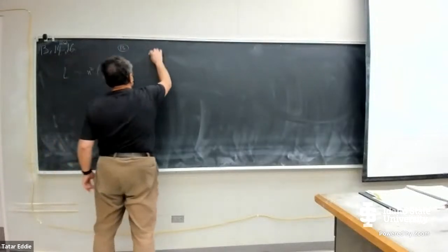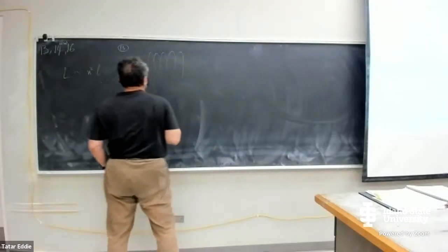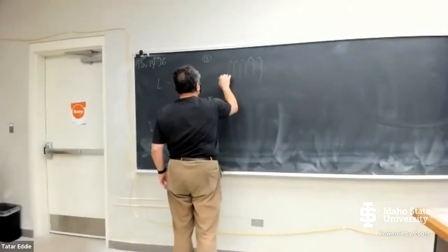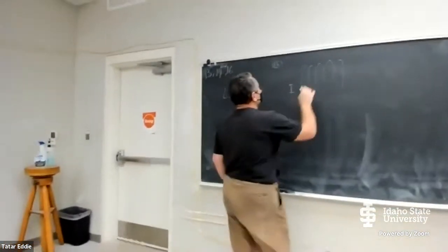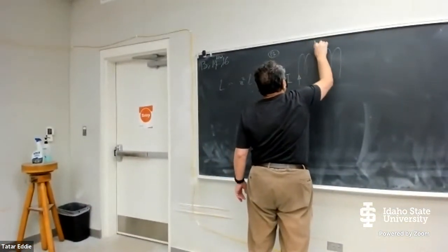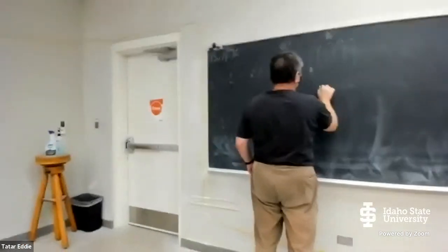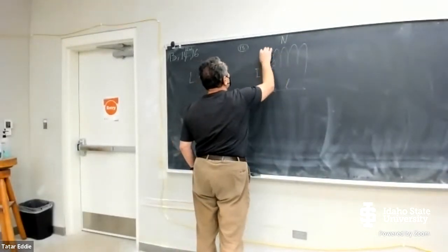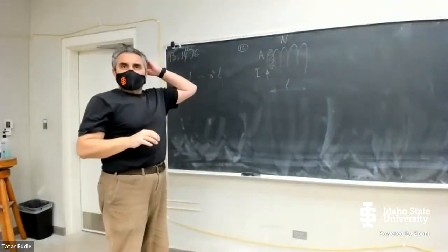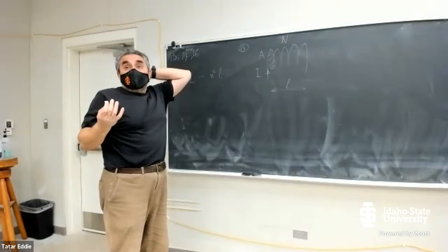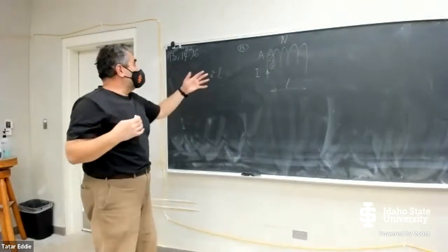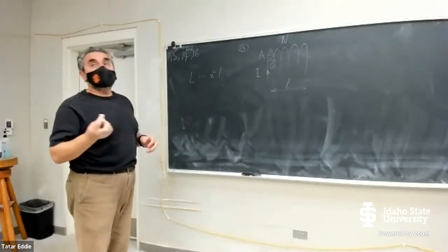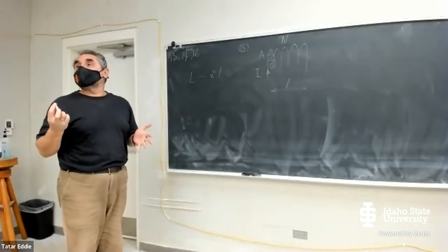So you have a solenoid. Let's say that in this solenoid, the current that is flowing is current I. Let's say that the number of turns is capital N. Let's say that the length of the solenoid is lowercase l, and the cross-sectional area of the circle is area A. So in order to derive the formula for inductance of a solenoid as a function of its size and number of turns, first figure out the magnetic field inside the solenoid.